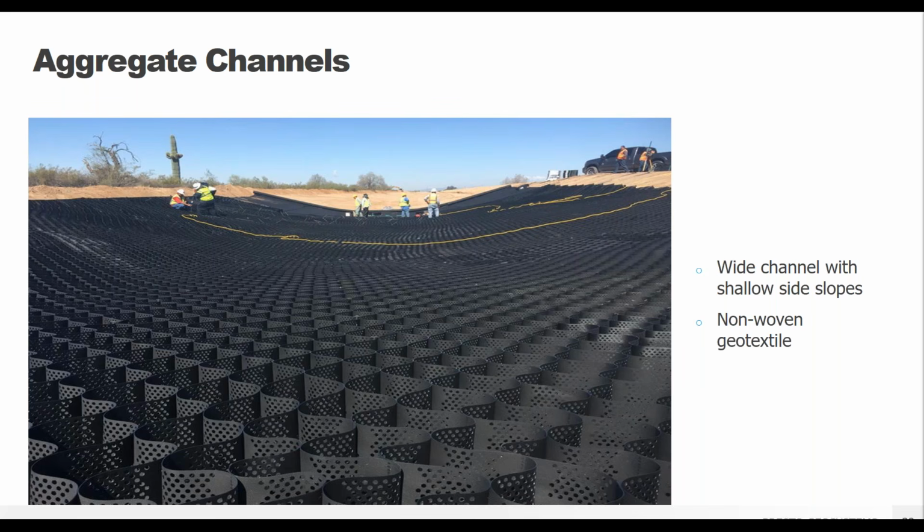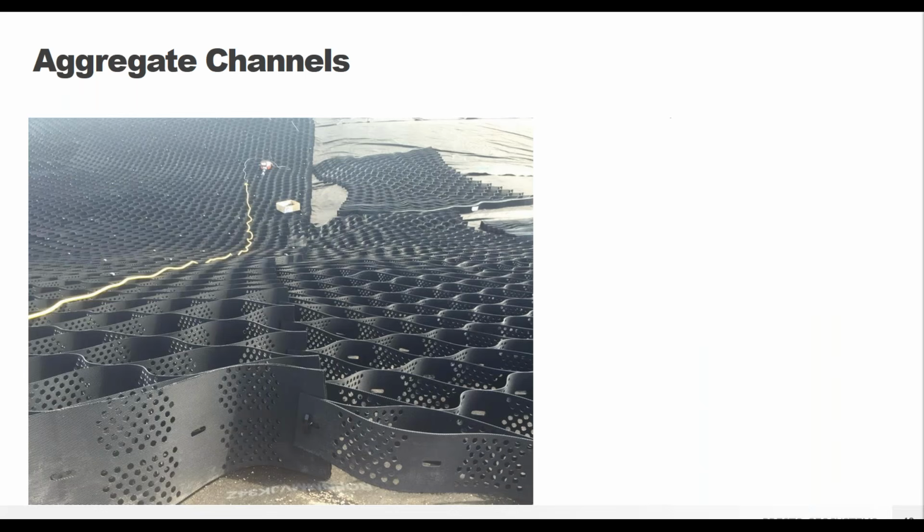This helps prevent the stone infill from migrating into that sand subgrade. You really want the stone to stay within the GEOWEB panels and not get lost underneath the system. And that non-woven geotextile just helps hold everything in place. So the channel was actually very wide and had quite shallow side slopes. So they were able to use stake anchorage rather than needing to use tendons. So that made installation a little bit easier for them as well.